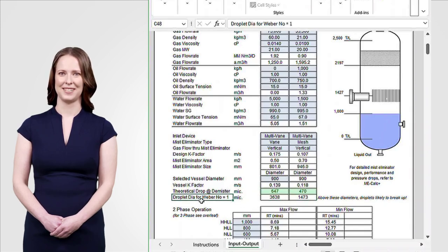Below this is the maximum falling droplet diameter that is theoretically achieved by the coalescing of lots of droplets together before it breaks up under drag forces. However, sometimes, due say to very low surface tension, the maximum droplet size can be smaller than expected. We therefore highlight the likely droplet diameter in a green box here, from the two calculation methods.